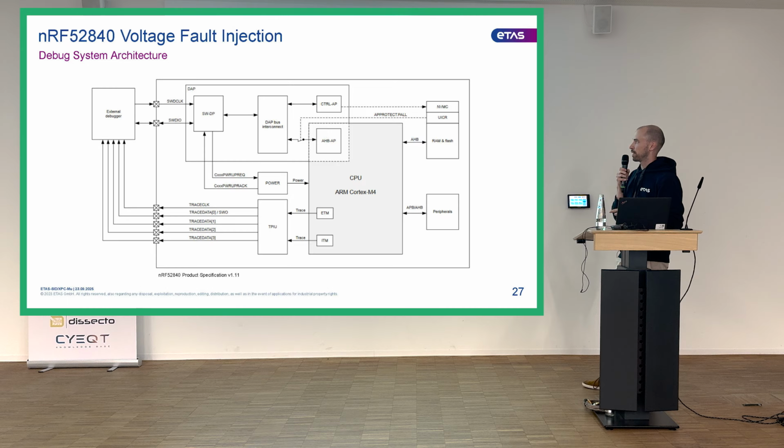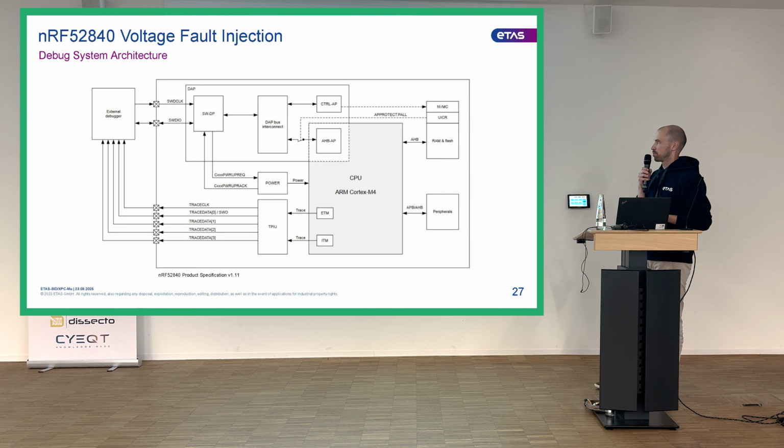So that's how I do the actual chip debugging. And we can see here that it can be locked. Based on a value that it reads out of the flash during boot, we can tell it to lock this access port, and then I can no longer debug the chip. This value is read out during boot, and there's not really a straightforward way to change it, because the flash is, of course, contained inside the die of the chip.